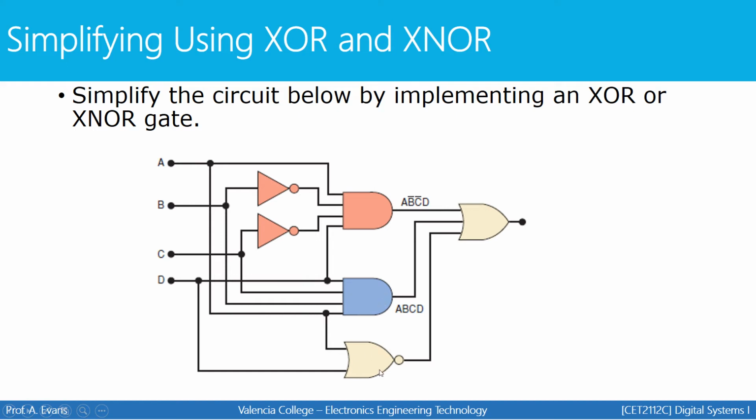And then down here we have a NOR gate. And going into the NOR gate, we have A and we have D. Keep in mind that the expression right here has been written after De Morgan's theorem has been applied. If you're wondering why the output doesn't look like this, that's because if you apply De Morgan's, break the bar, change the sign.